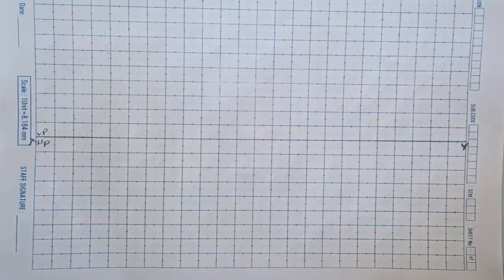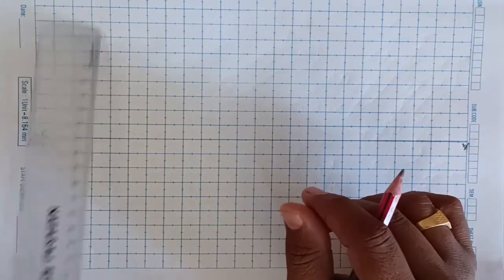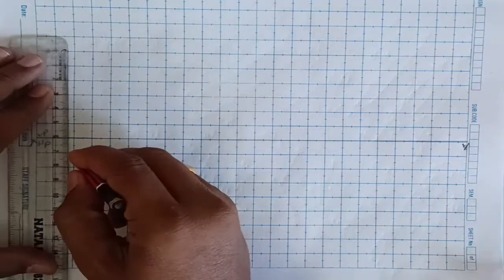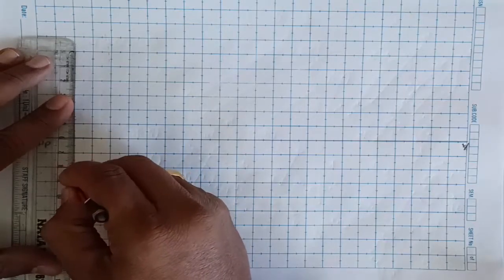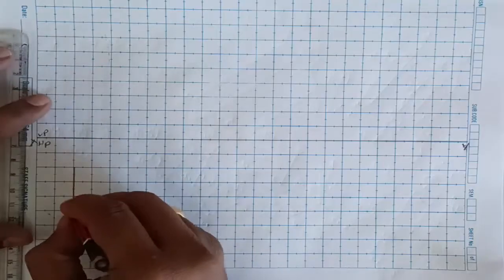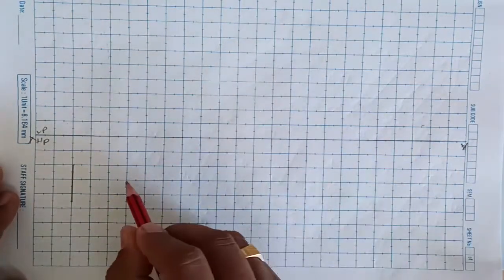Okay, first we need to check the resting condition. Here, for the resting condition, they have given the corner. So the corner should be taken on the right side, and the edge will be taken from the left side. The length of the pentagon side they gave is 25, so we can start from here. We need to take the edge here. Once you take the edge on the left side, the corner will come on the right side, so it will satisfy the condition.